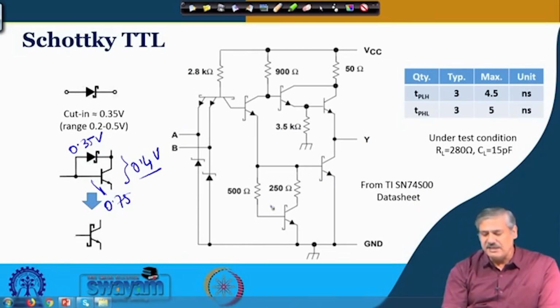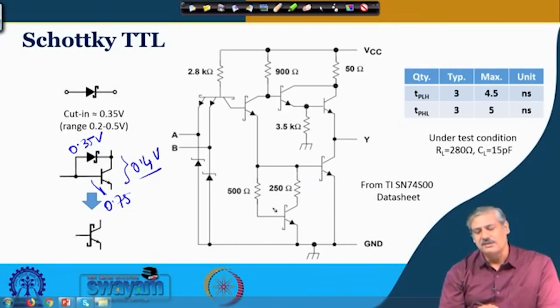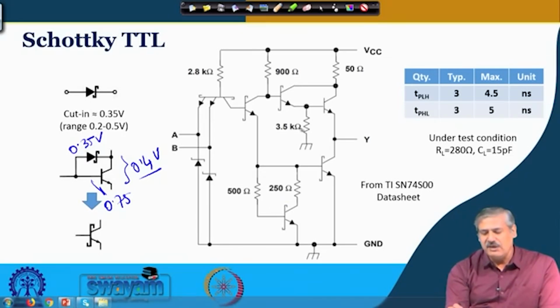Okay. In addition, over here what you see is that earlier there was only a resistance, okay, from this T4. Now, there is an active pull down. So, this helps in taking away the charge from this base emitter junction when it is coming out of saturation, whatever level it goes into the saturation. And the other thing over here what you see is a Darlington pair configuration, and you do not need a diode over here, because there are two such things.